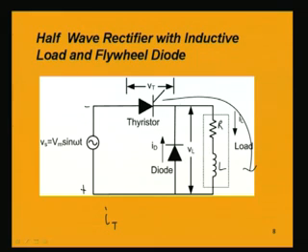The diode is conducting. The voltage across this diode is 0. We are also assuming it as 0 because it is very small, 0.7 volt, it is almost 0. So, the voltage across the load is the voltage across this diode, which is 0. When it is in the negative half cycle, the voltage across this load is 0.